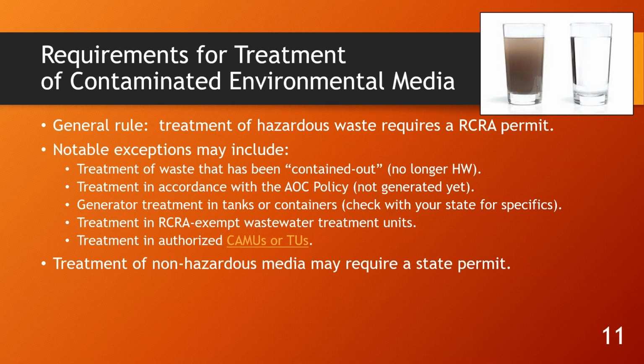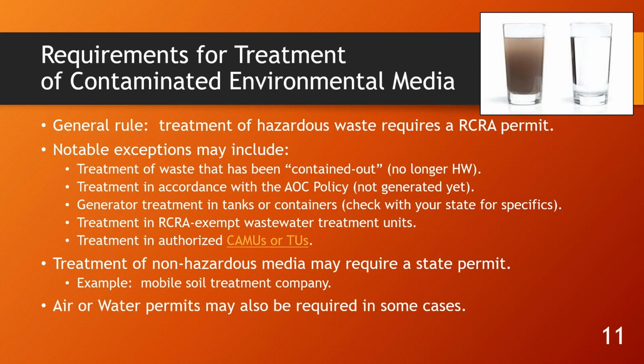Now, of course, just because it's not regulated federally under RCRA doesn't mean you might not require some permit in your state. So let's say mobile soil treatment. Air and water permits may also be required, like for soil venting or groundwater pump and treat.